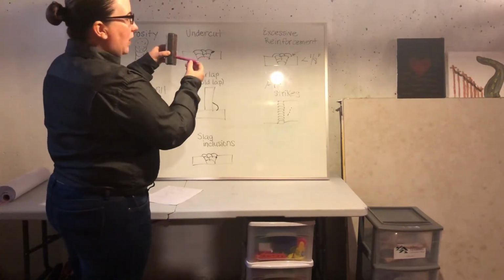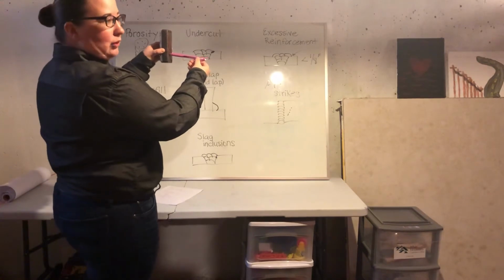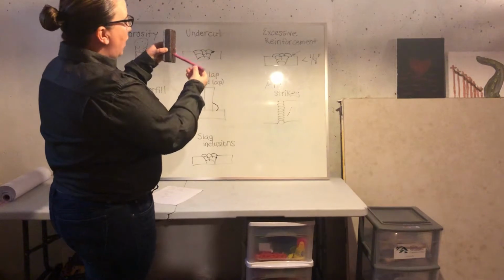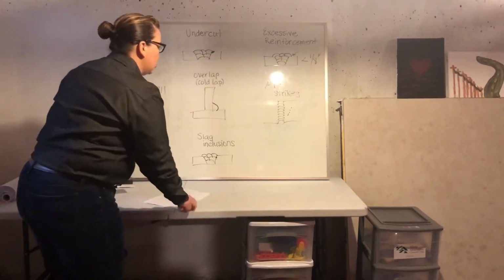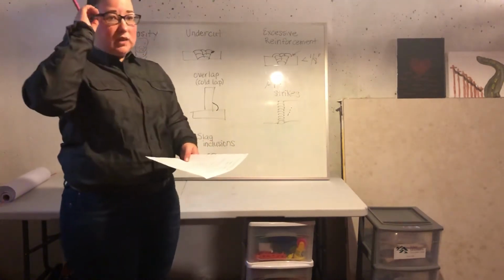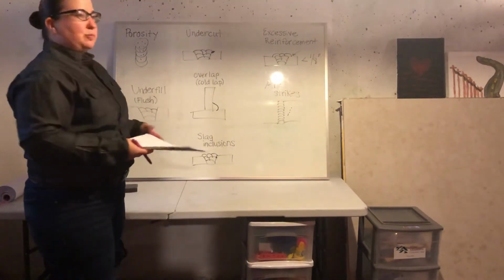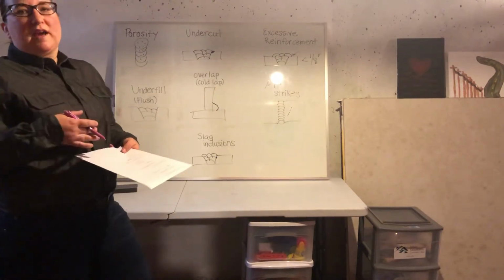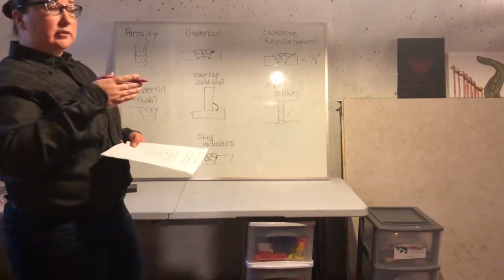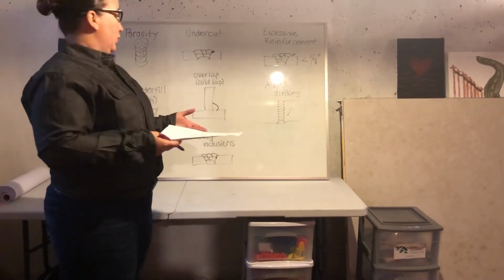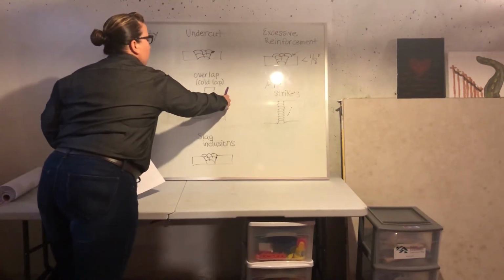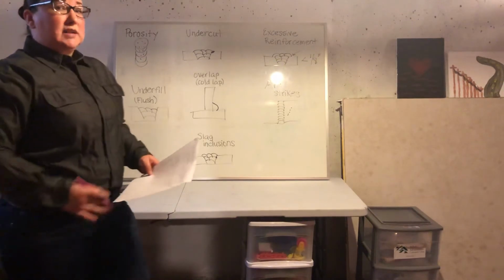That's where in the weld joint I am pointing that electrode. That work angle is equally important. So you can see you have an x-axis and y-axis that you're creating angles over. We really want to pay attention to those things. Another human error is your positioning. Where are you pointing that filler metal? Not just the angle at which you're pointing it, but where are you placing it in that groove, or if you're in a T-joint, where am I placing that? Am I placing it up more on this vertical plate or more down on that horizontal plate? That's really important.